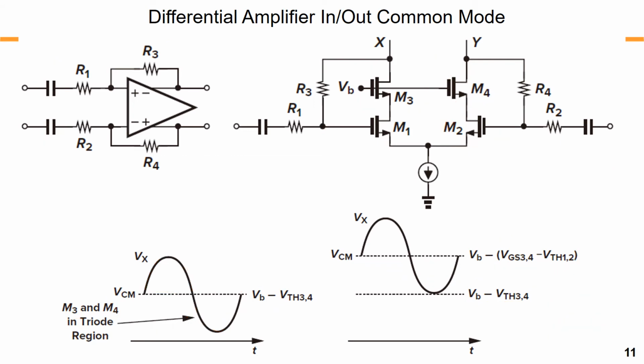So calculating swing range, there's a miscalculation. If you cancel it out, then what? You get the minus VGS 3,4, and it would not cancel times 2 times VTH. Let's say times VTH 1 and 2 plus VTH 3,4, right? That would be approximately what? 1 VTH minus overdrive, right? So that would be the amplitude you would expect in this case, right?